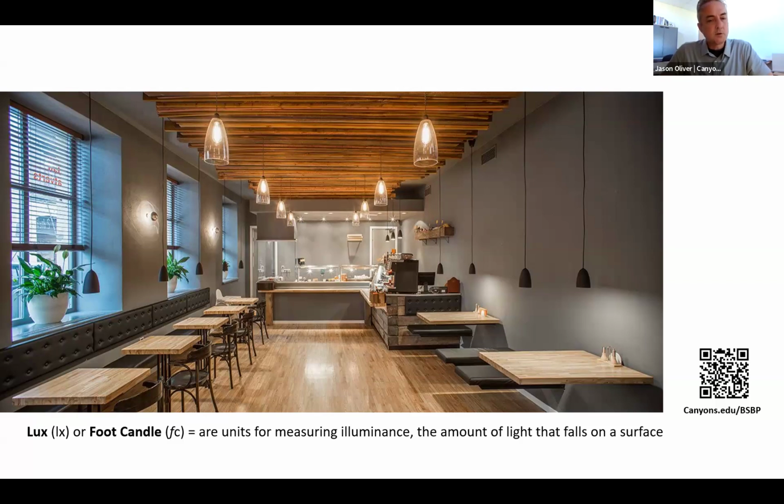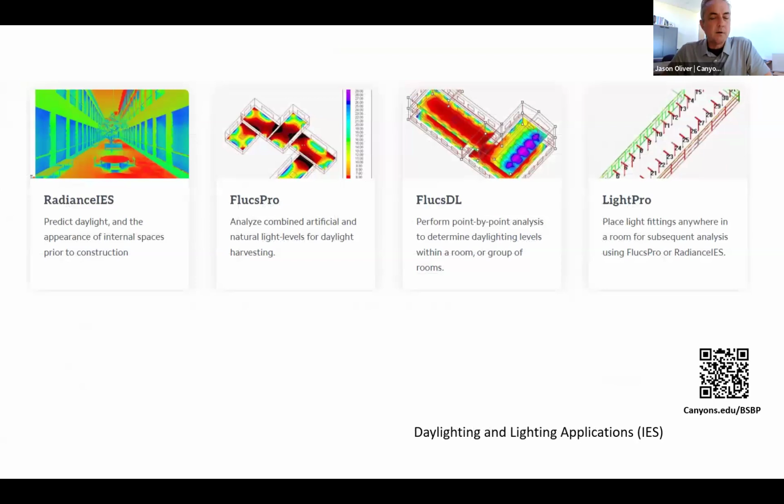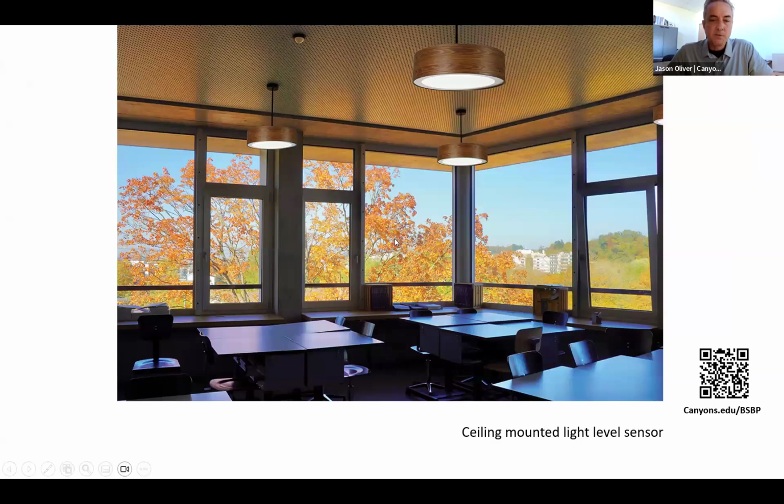Up until recently, as an architect, we would have to wait to have a conversation with a lighting designer or electrical engineer before we could really get into a qualitative design or assessment of the light levels. But now, with the software, we can look at whatever the target foot candles are, whatever the light levels are, the illumination for a space, depending on its use. In this case, we use the ISVE Radiance tool, and we can do some pretty elaborate ray trace illumination studies in the virtual model. So we can see what the various foot candles are at different surfaces, from different parts of the space. We can detect glare, so we can see where glare is going to be an issue.